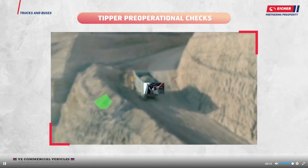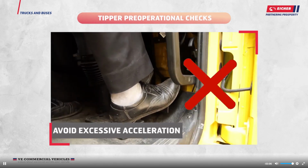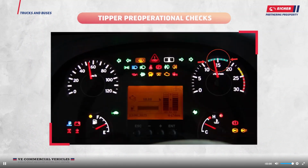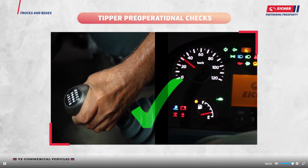Fuel-saving tips: always move the vehicle using crawler or first gear as per load and road condition. Avoid excessive acceleration. Avoid resting your foot on the clutch pedal while driving. Drive the vehicle in the economy zone for better fuel mileage. Always use the right gear for the right speed as recommended.